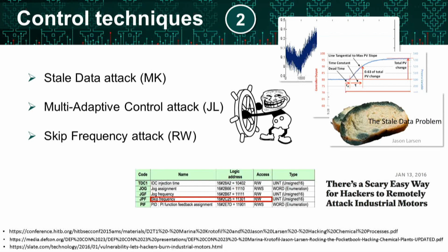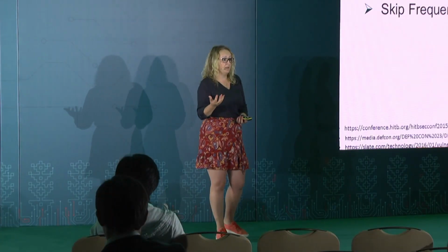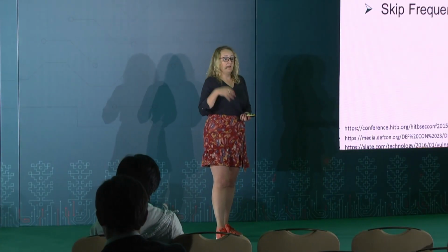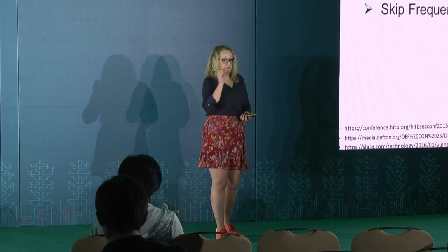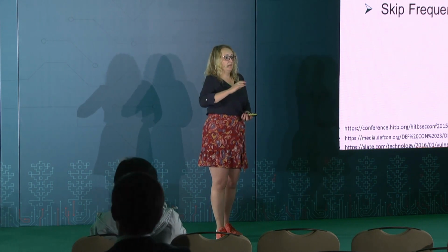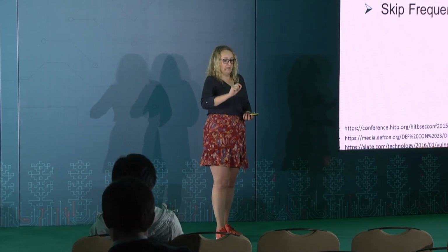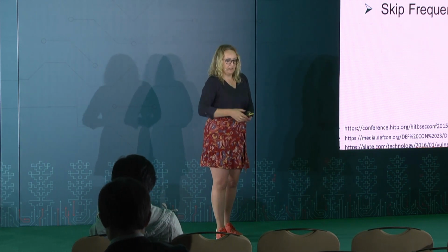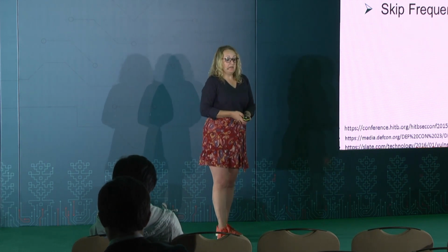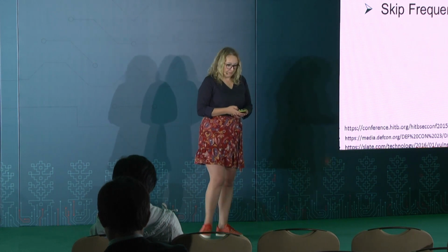The third technique is the skip frequency attack, which was discovered and presented by Reid Whiteman. In this case, all rotating equipment has native frequencies at which it starts to vibrate. These frequencies are unique to each piece of equipment. You will find them in the manual, and then in the control logic, those frequencies will be specified. Even if you try to change the frequency, you will always skip this one because it will cause vibration. But at this frequency, the equipment can be destroyed very quickly.